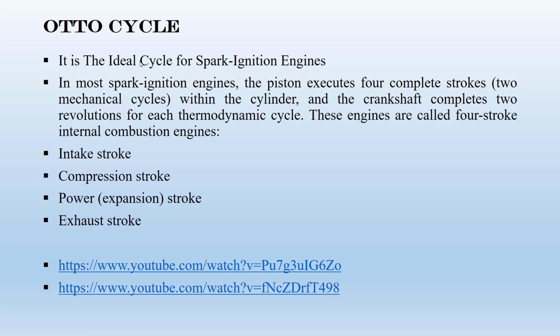The 4 strokes are, first, the intake stroke, in which fuel and air are added to the cylinder. Then there is a compression stroke, in which the fuel and air mixture is compressed.